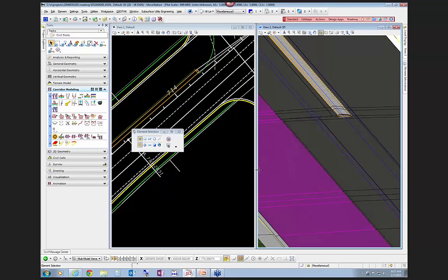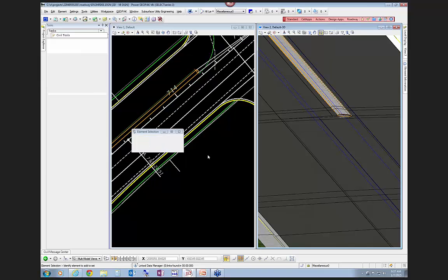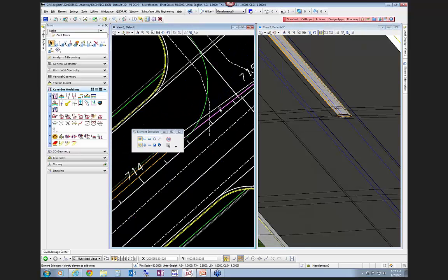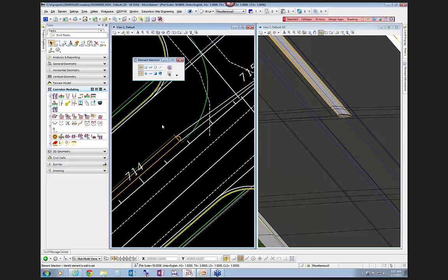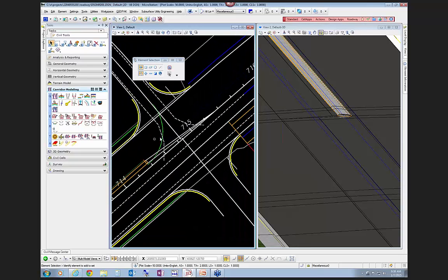So what I've done is, in the plan view, I've come out here and added these two slope break lines, because on the other side here my template's going to be balanced. It's basically going to be crowned about my center point. So what I want to do is take those two edges and transition this 2% slope, which is in here, to this line until it meets here. And then the same thing with this one, I want to transition it to this point right here.